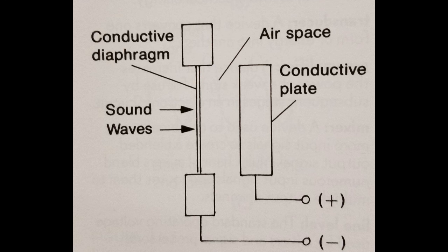When a sound wave strikes the diaphragm, the pressure changes the spatial relationship between those two plates. This causes a change in the condenser, which changes the voltage applied across those two plates. That voltage variation mimics the pattern again of the sound waves generated from the source.